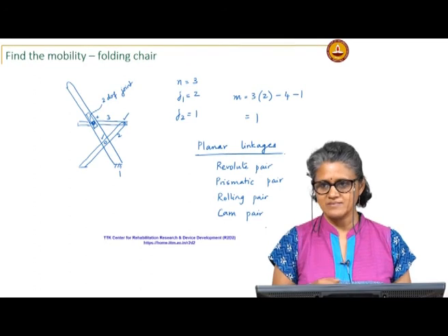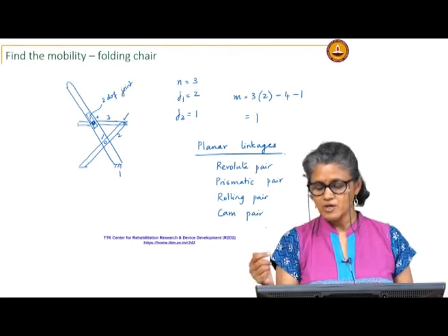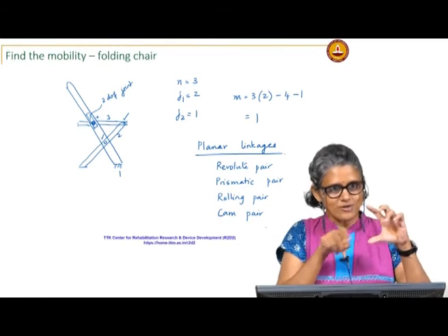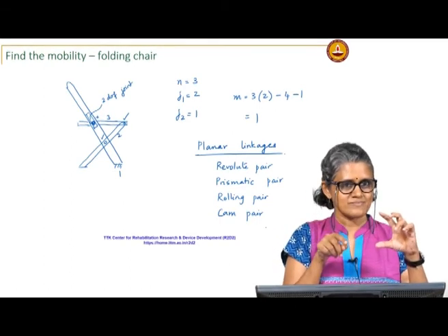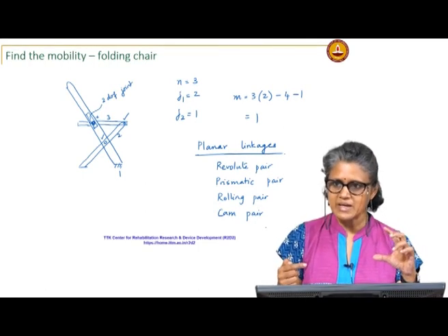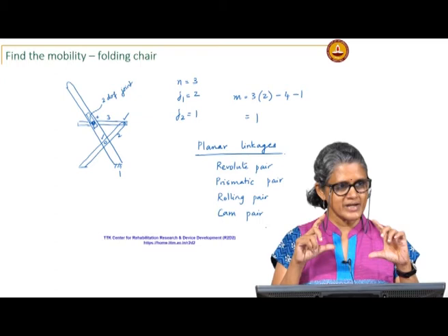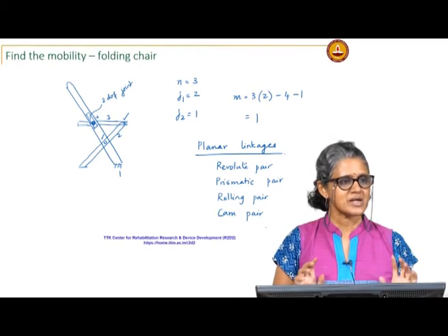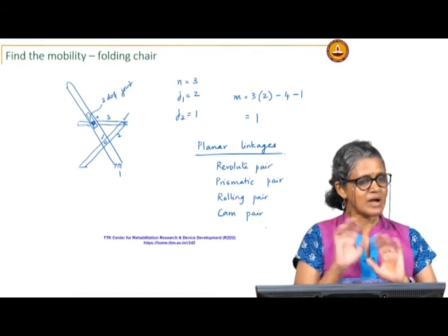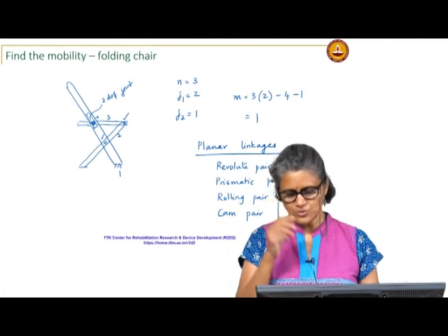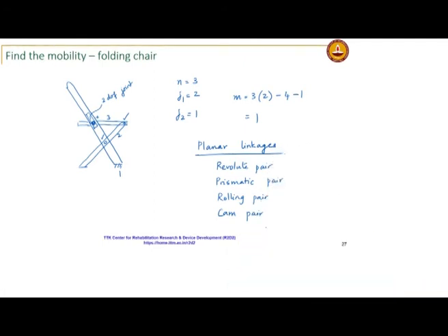So, it can change how it grips. So, that screw joint you would not consider as part of the mechanism itself, okay. That is a separate thing that is used only to adjust this planar mechanism. So, even though the joint exists in the planar mechanism, it is not part of the kinematics of that 4 bar. So, you have to be able to differentiate between which joints belong to the mechanism that you are analyzing.